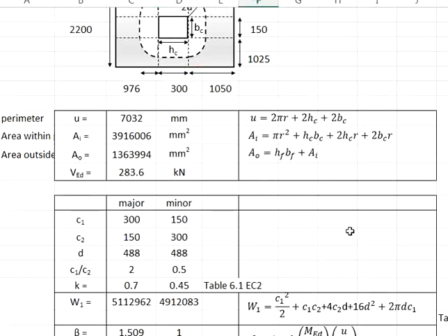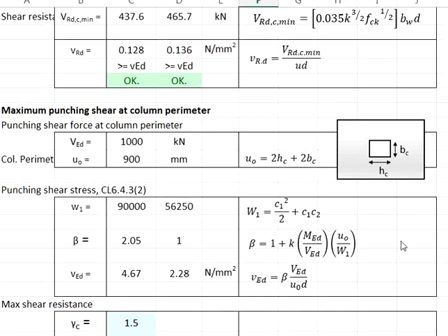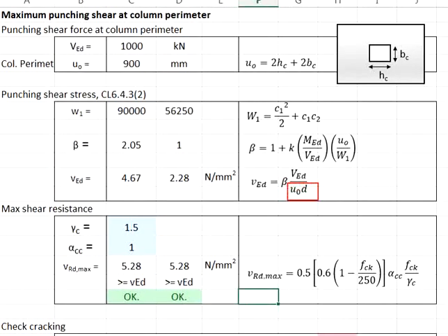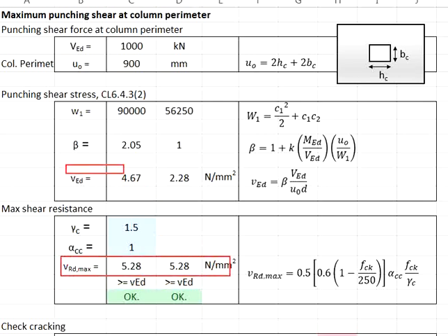Having the effective depth increased, now you will have a greater effective shear area taking the shear force. This will result in lower shear stress, and you will have to test the appropriate thickness of the pad footing until you come to a state that the shear resistance is greater than the shear stress.